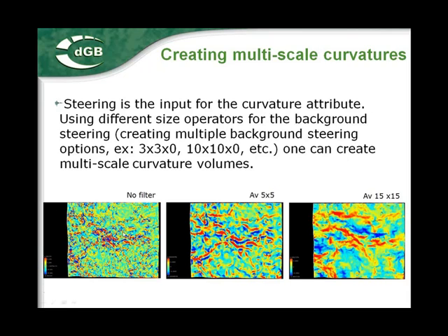Here this is the output of a curvature attribute, the maximum curvature, so I display the largest principal curvature of the two curvature directions, which is the very large maximum, positive or negative value, depending on whether you have concave or convex bending of your surface.